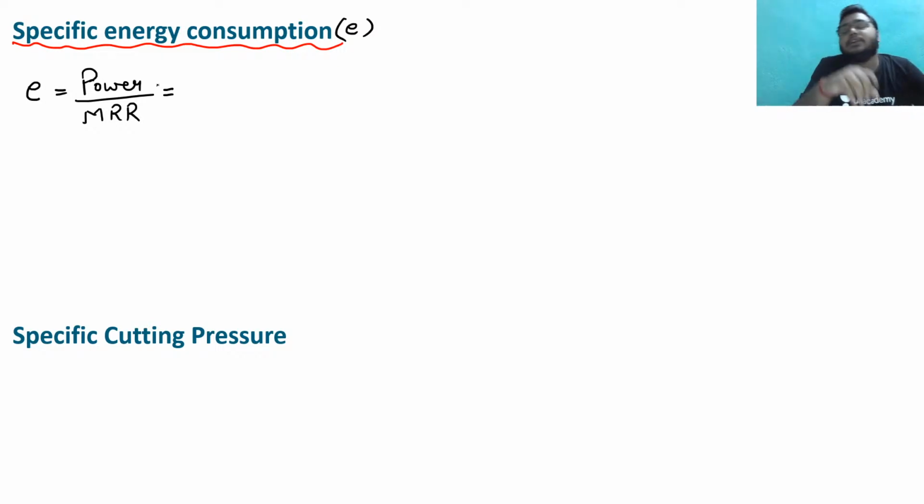If it is mentioned in a question that everything is given and you have been asked to find the power, you have to assume that the examiner is asking about the cutting power, because we have seen 99% of the power consumption is due to the cutting force. So I hope these things are clear to you. So power is going to be Fc into V. Clear?